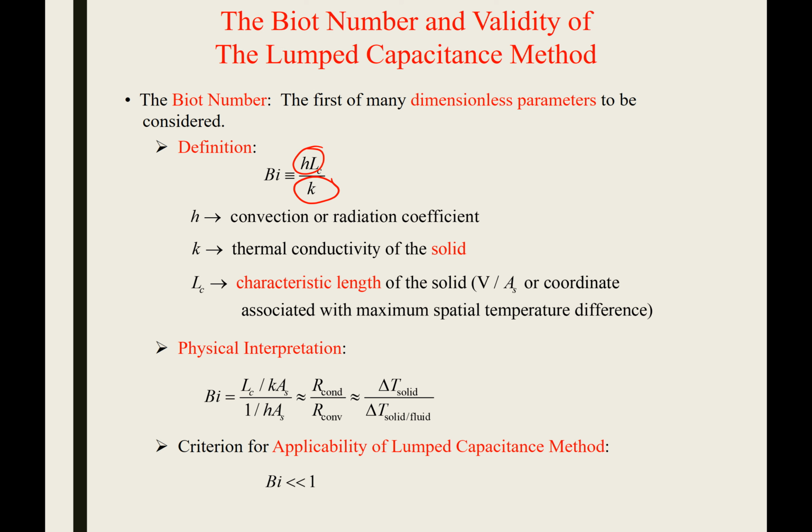However, they can still come in handy in helping us qualitatively understand what goes into the Biot number and how fast one thing is happening relative to another. So the Biot number is the conductive thermal resistance divided by the convective thermal resistance. If there's very low conductive thermal resistance, heat is going to conduct through your solid very quickly, making your Biot number very small, meaning you could apply the lumped capacitance approximation to your system.